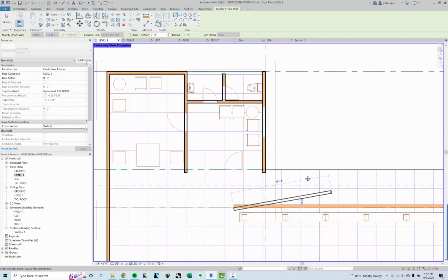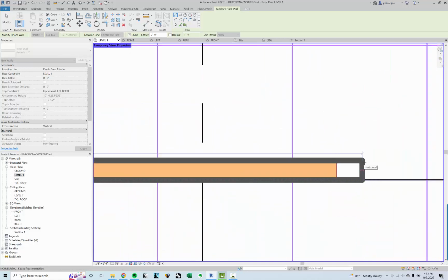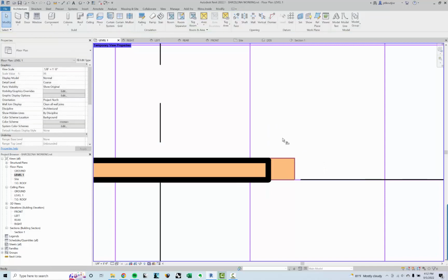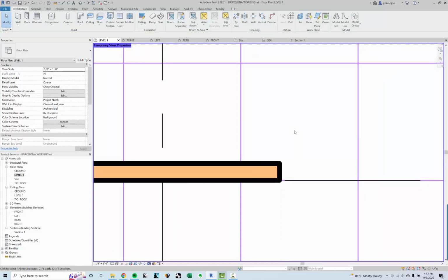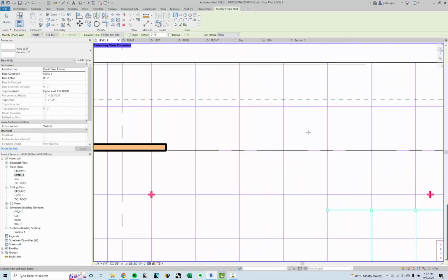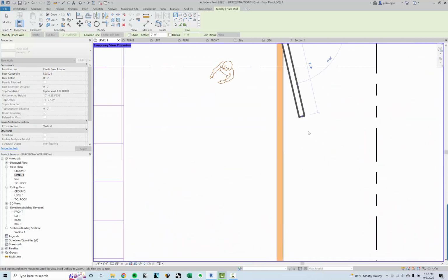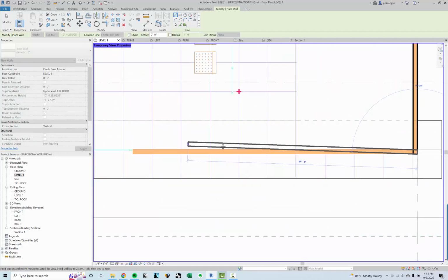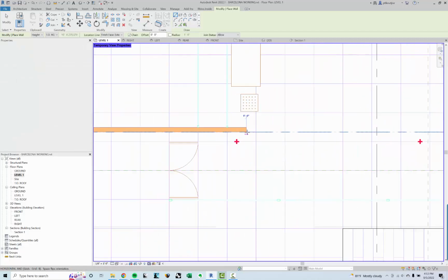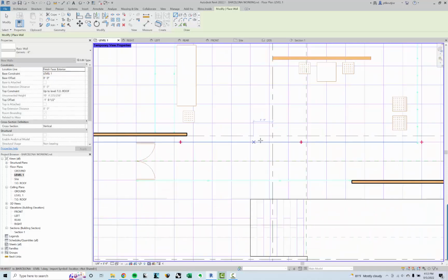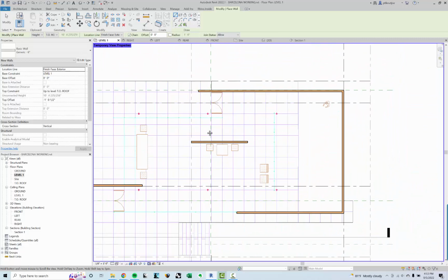So like I said, you just go right over the doors, hit spacebar. Now, let's just say it's not snapping right. I can do align, AL, and now it's good. And then another shortcut, which, like I promised I wouldn't use, I hit WA and I get wall, and I'm back into my wall drawing and just tracing this all around. That will do at a curtain wall. And then this, I think this is that marble interior feature wall, but we'll just keep it as that for now. We can change it later.